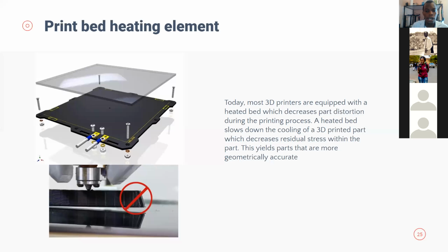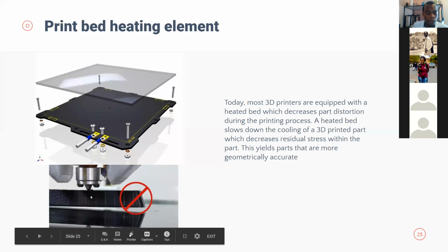So that is how it looks in short. You can see over there that if you don't have a flat surface, then you are going to print your part, but there is going to be space left. And when there is space left, your part is going to move during the printing, and then the printing will stop. So you are going to destroy your part if you leave space between the printed material and the substrate. So you need to have the surface as flat as possible.